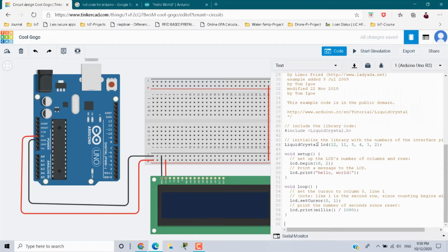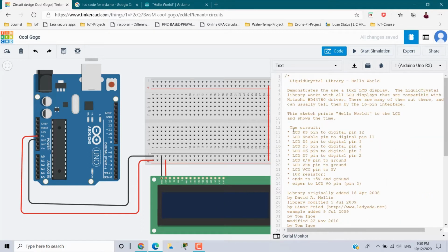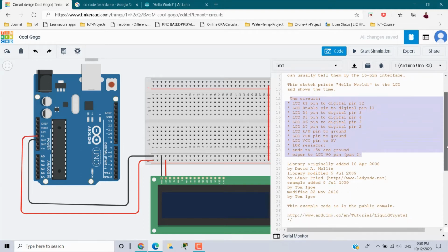So here you have the circuit design instructions, how you have to give the circuits. Based on this we have to connect it here. First LED cathode, which is negative, so take it and give it here in the negative slot and make this black color. And the next is LED anode.